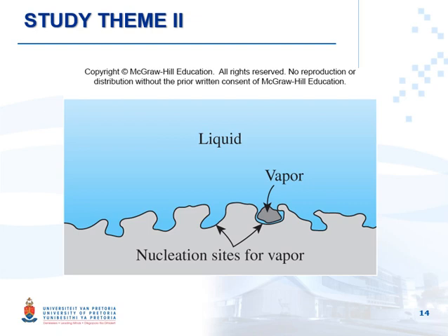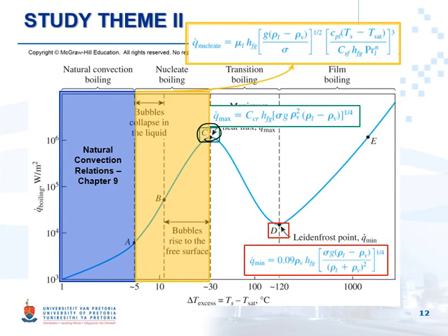We said that one reason is that the rate of heat transfer will increase, but it's not sustained. It will be very high maybe for 1 or 2 seconds, but not all the time. And the other point is that everything in boiling we design for this point C, which is not even close to film boiling.